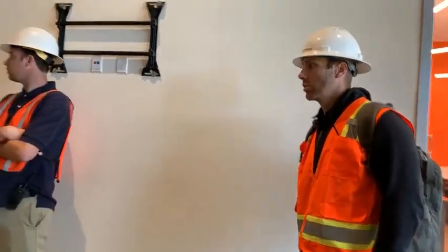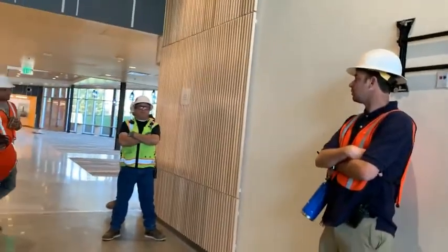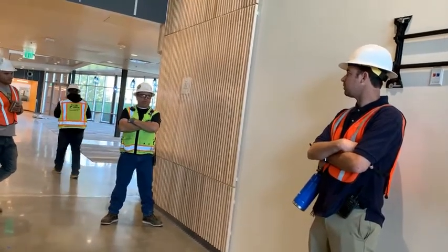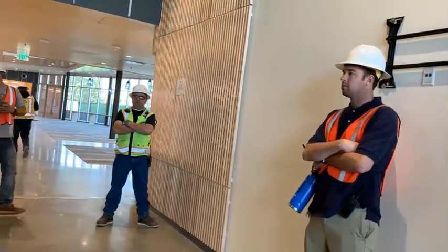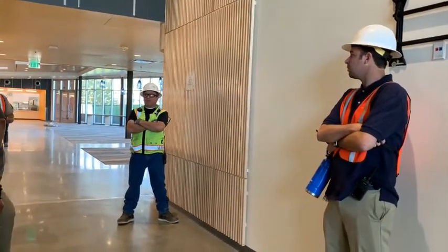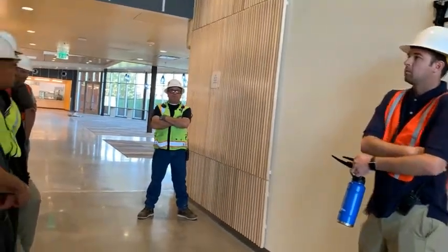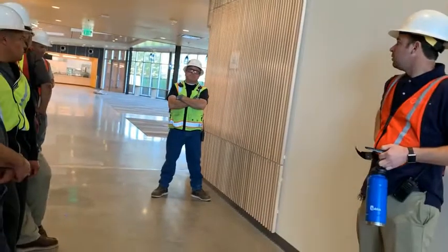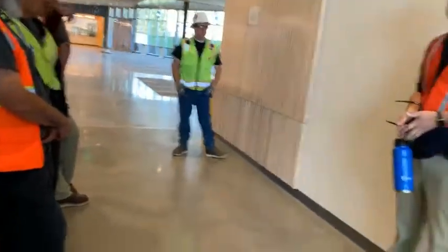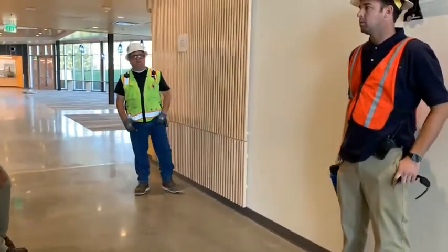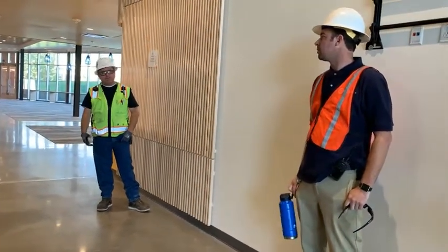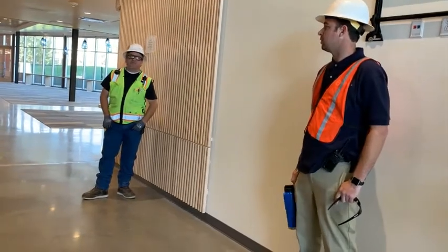And the switches in the restrooms here have been overridden so that you can't go in there and turn the lights off manually. So they're just on the aux sensors? Yes. For safety. Yeah, they have their own switch. It's still part of the M-Light system. They're not line voltage. No. They're still part of our system, yeah. So they're still connected to bridges and whatnot. Yeah, exactly. But they're programmed not to be operational, because they don't want anyone going in there turning the lights off. They'll just turn off by themselves.